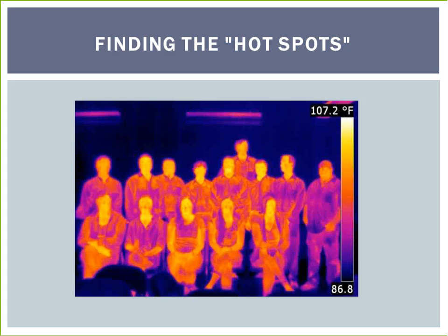A camera-like device views a large area at a time, senses infrared emissions, and converts the emissions into a visual display. The equipment remains in operation, so production is not interrupted. Hotspots can be pinpointed quickly, saving labor and cost, and targeting plant maintenance where it is needed.